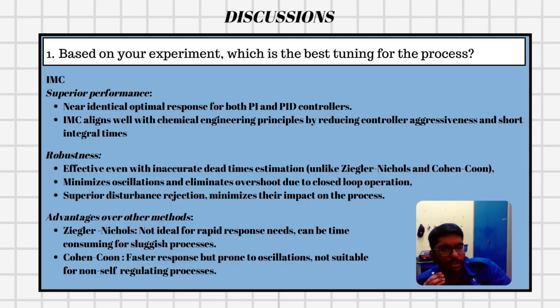Based on the experiment, we found out the best tuning is actually IMC in comparison to Ziegler-Nichols, because Ziegler-Nichols is not ideal for rapid response needs, while Cohen-Coon has faster response but is prone to oscillations. So it's not suitable for non-self-regulating processes.